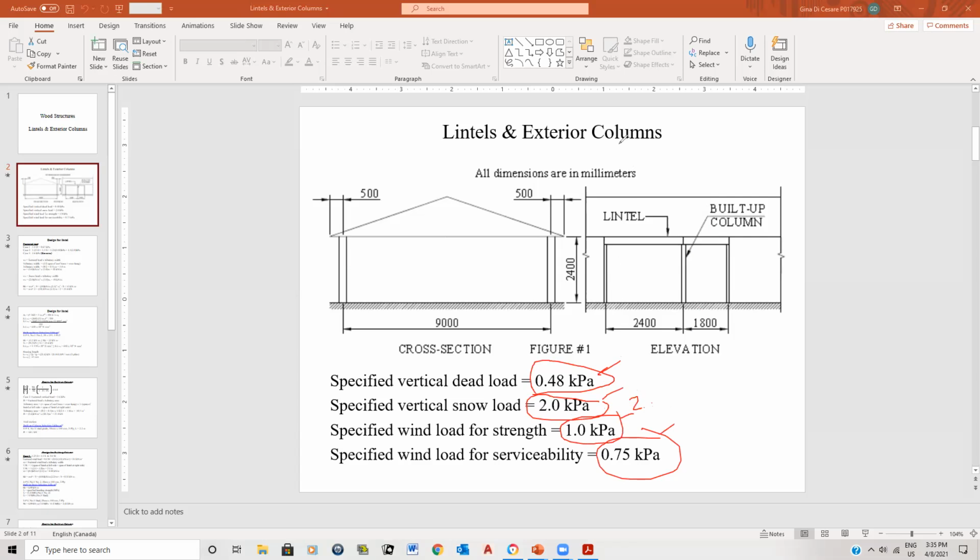I don't know if you guys are interested, but the National Building Code is very limited when it comes to being very specific. If I can find it, I can send you a document that gives you the snow loads of almost every town in Quebec, which is nice to have. If you want that, just let me know, and if I can dig it up, I'll be more than happy to share it with you. Because if you happen to find a town that's not in the back of the National Building Code, getting the information is going to cost you about $300 if you ask Environment Canada. It's up to you. If I can find it, Omar, I'd be more than happy to share it with you.